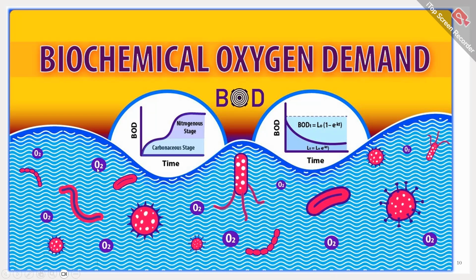That is not the molecular oxygen of the H2O, that oxygen they are not taking. They are taking only the dissolved oxygen, which has been dissolved in the water with the help of the waves basically. Because of the turbulence at the surface of the water, the oxygen gets dissolved inside the water, and that oxygen is taken up by the aerobic microbes to decrease the BOD.